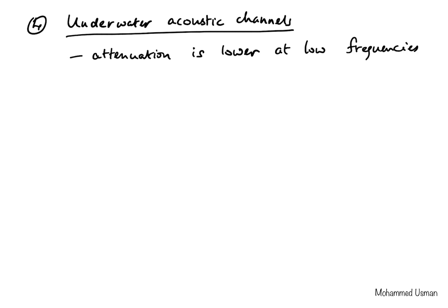In fact, the attenuation is lower for low frequencies even in the wireless case, but in the underwater case, the attenuation for higher frequencies is even more severe. So therefore, it makes practical sense that for underwater communication, lower frequencies are used. So attenuation is lower at low frequencies.